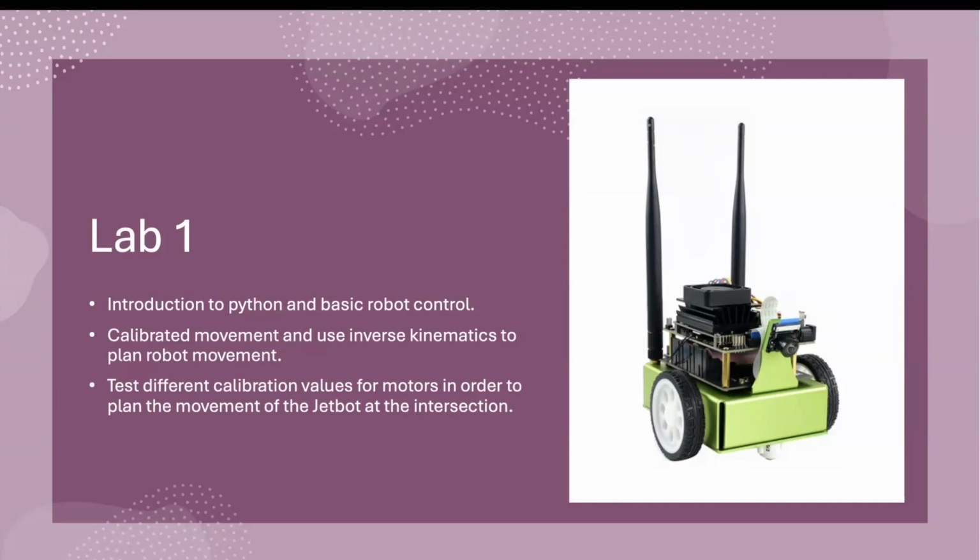To solve this, we performed manual odometry calibration by timing the robot as it traveled over set distances on a straight driveway. The issue was that sometimes, even though we had the same input for both motor values, so both the left and right, we would see some drift from the robot. So in order to fix this, we developed a calibration table and applied specific values for the bias, ranging between 0.028 and maybe 0.019, to ensure that the robot maintains a perfectly straight heading.